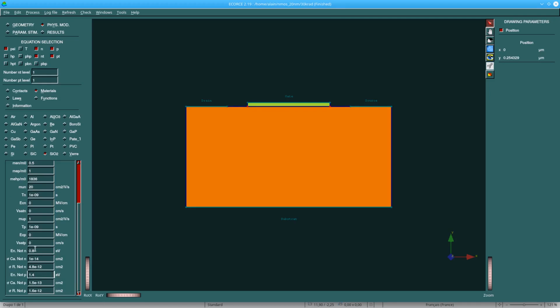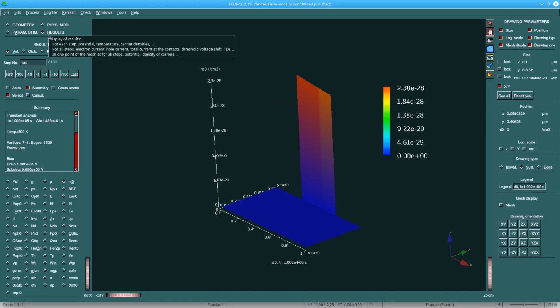That's to say that by thermal re-emission, we are able to free all electrons that are created inside the oxide, while holes that are trapped inside the oxide stay locked inside, so we have a net positive charge that stays in the oxide after radiation. I can also calculate the ID of VGS characteristic after applying this radiation.